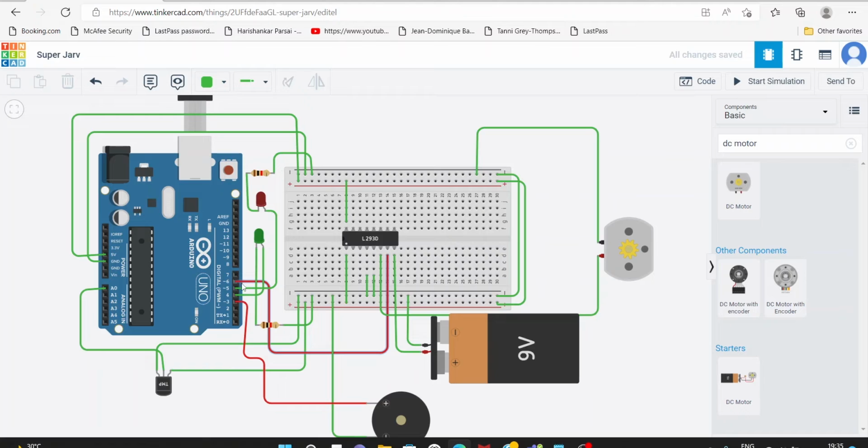Here we use digital pins to power our LEDs through resistors so that the current does not exceed the rated current, and then we have also connected a piezo buzzer which will create sound the moment the temperature has crossed a certain threshold. The green LED keeps glowing until we are in the safe range of temperature, and the moment it crosses the threshold, the red LED starts glowing.